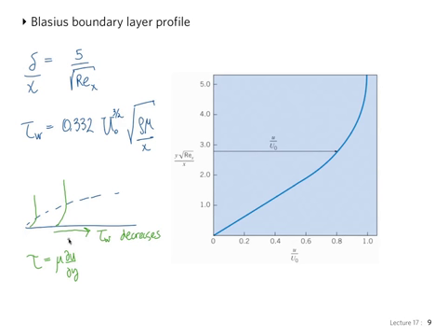Now at some point along the wall, the boundary layer is going to become complex. The flow develops differently, it becomes turbulent, and so when it becomes turbulent, what you have is lots of different eddies of different sizes which transfer momentum. The transfer of momentum is much more efficient in the turbulent case. And because the transfer of momentum is more efficient in the turbulent case, the turbulent boundary layers are generally more compact.